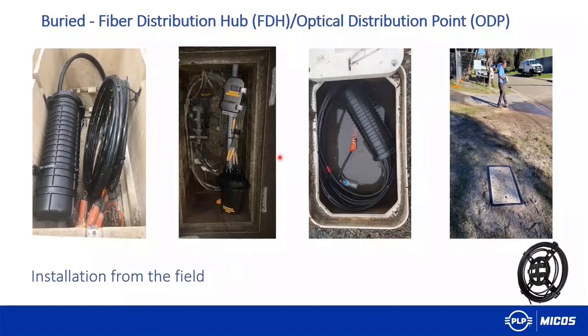And you can see those manholes are usually not IP68 rated, so the water can get inside at any time. That's why the closure, or dome closure, needs to be IP68 rated. And it is always important to leave the slack inside the closure for one simple reason. When you want to do the reinstallation or add customers or whatever, you pull out the closure, you have